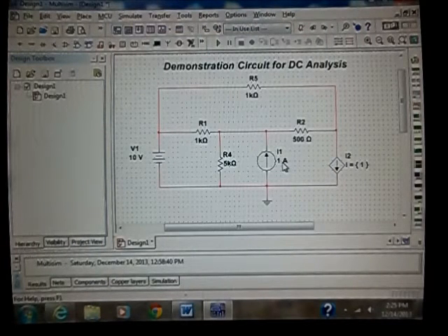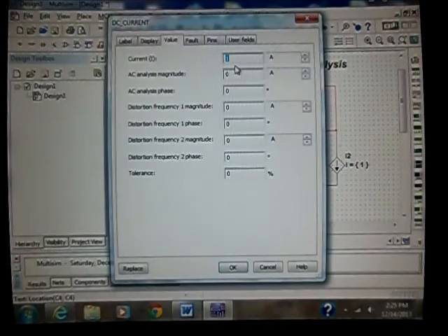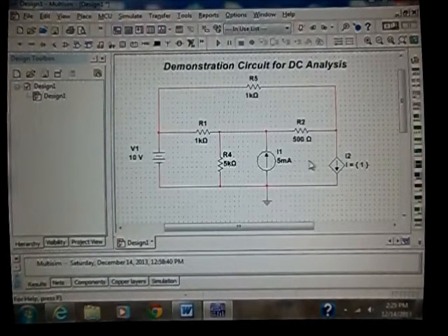Let's change this to 5 mA. Left clicking, 5, and then click the box here to get to mA. And now it's time to do the harder part, which is to set the strength of the ABM source to make it into, say, a voltage-controlled current source.